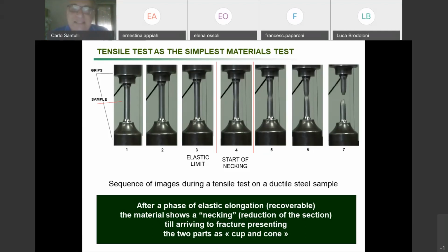The plasticity can be for a longer time or for a shorter time, and this depends on the characteristics of steel, because there are a number of types of steel, of course. We can go into more details later on, but please be aware that not all types of steel behave like that. This steel is not particularly brittle. When we say brittle, in operational terms, brittle means that it breaks suddenly.